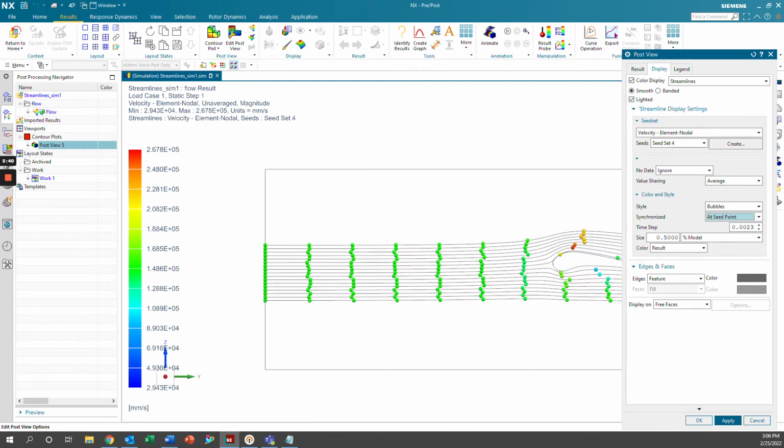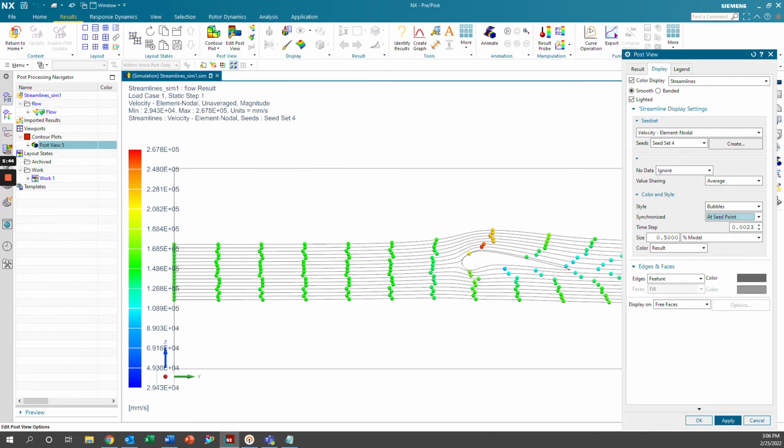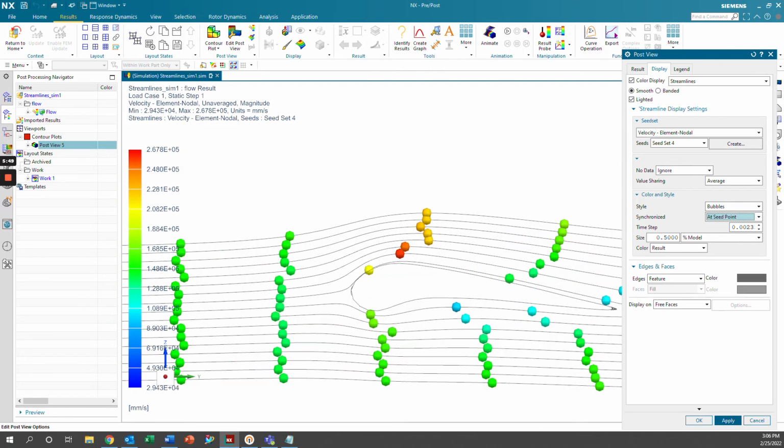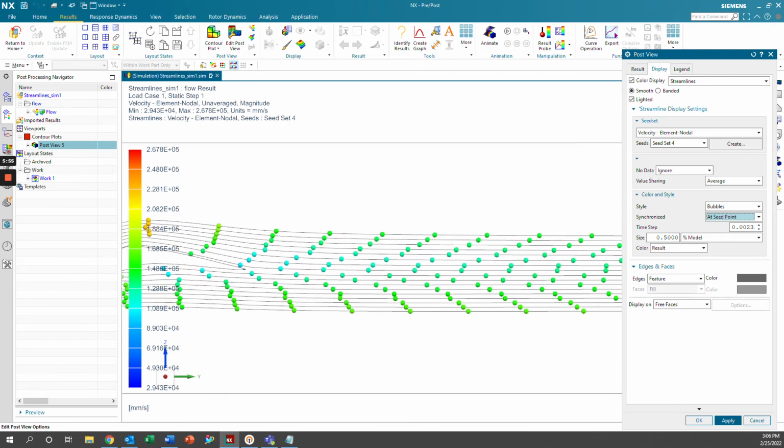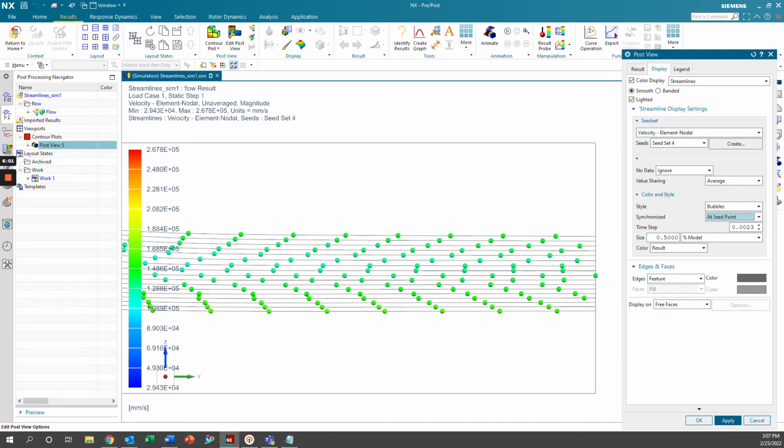And each column here represents what's happening at each part of the flow field at each position. So you can see here, the bubbles start to separate from each other because there's different amounts of velocity as you go up and down. This is showing some of the viscous effects from the airfoil. And then you can see in this wake here, the wake has lower velocity than the surrounding area, and so these bubbles are staying behind as these have a higher velocity.